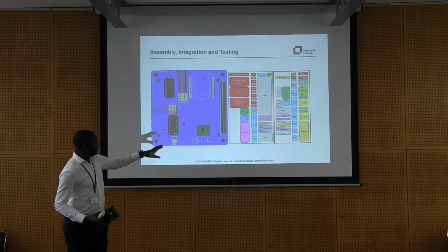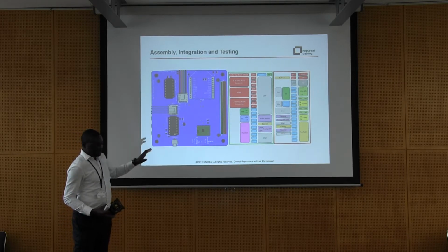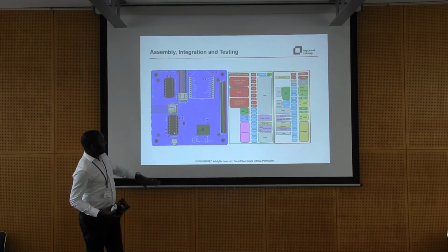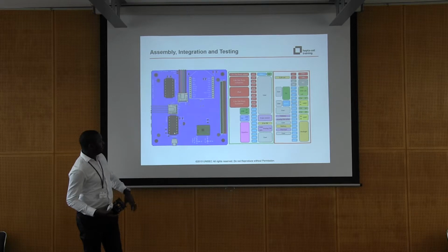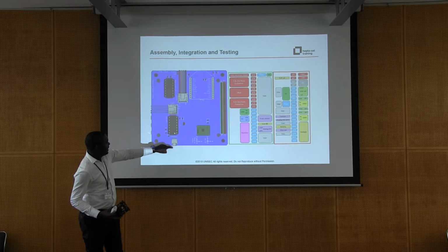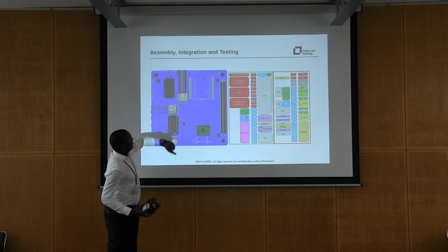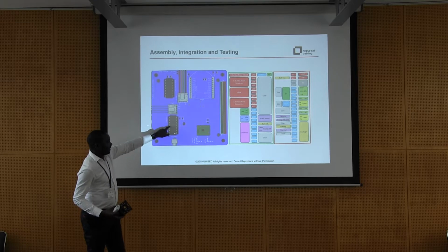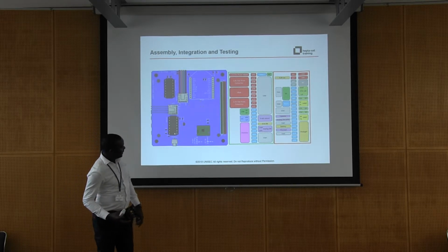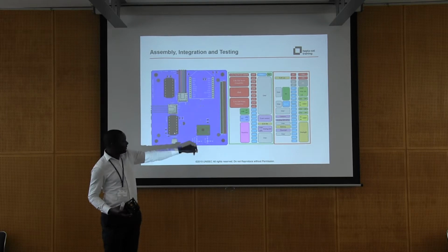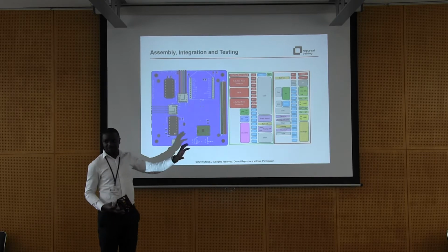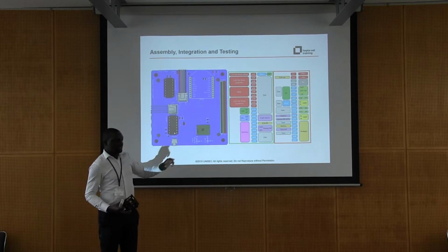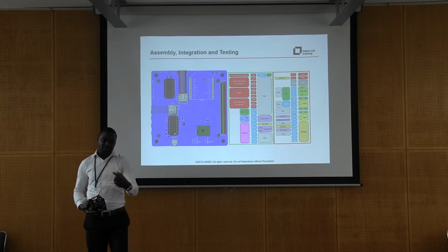And this is what it looks like physically. This is in the book, and you will see the pin assignment that you should use in order to communicate with the embed. This is the sensor board which you are going to install. You see the thermal sensor is here, and you see the camera and the GPS. And there is an analog switch for them. And this is the amplifier for the thermal sensor. Then the 9-axis sensor is here. It's very important that you pay attention to the orientation of this sensor because it has some axes, but it's drawn for you to see in the textbook.